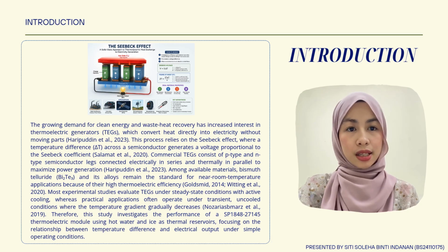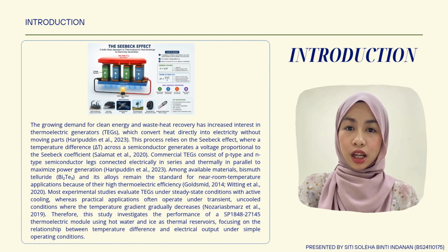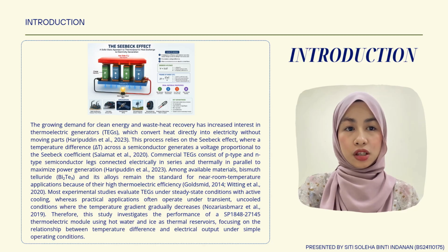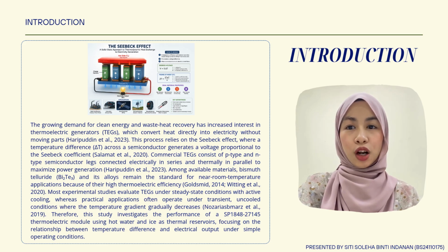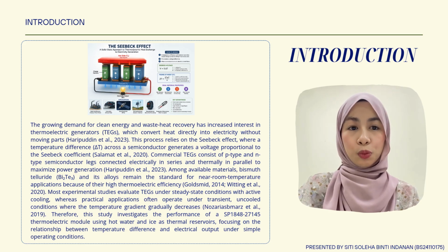Although many studies test these devices under controlled laboratory conditions, with active cooling, real-world applications often operate without active cooling, causing the temperature difference to decrease over time. Therefore, in this experiment, we investigate the performance of an SP1848-27145 thermoelectric module using hot water and ice as the heat source and heat sink. Our main objective was to study how the temperature difference affects the electrical output of the module.